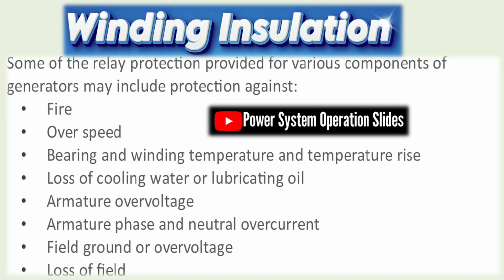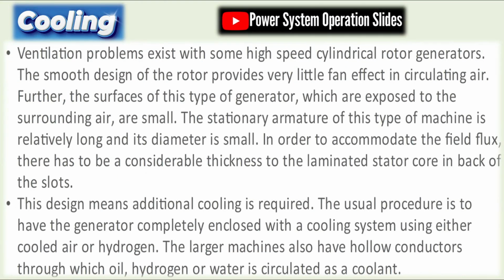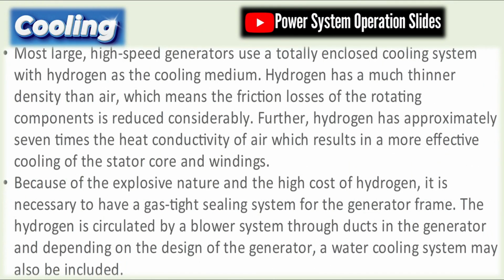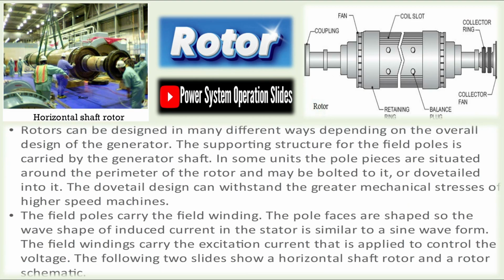Wind turbines use rotor blades connected to a gearbox and generator. Their output varies with wind speed. Modern wind turbines feature pitch and yaw control for performance optimization and grid stability. Internal combustion engines, diesel or gas, are used in small-scale or distributed generation, emergency backup, and isolated grids. They offer quick response and ease of installation but are less efficient and have higher maintenance needs.